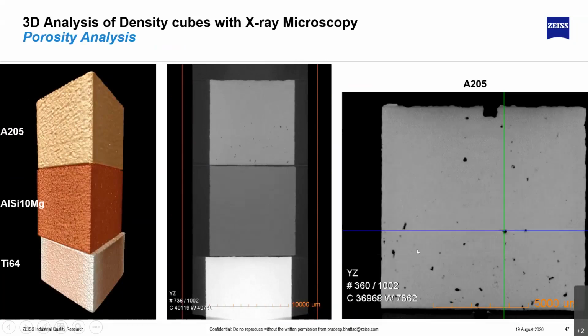So if you were to just take a cross section, if you look at the coupon at the top, if the cross sections were to come from the bottom or sit through the middle to the top, you'll get 3 different answers, and each one gives you an extremely biased answer, saying very bad, very good, to middling. So adding along with the tomography, if you add optical CT imaging, optical imaging, it tells you the sources of bias if there is any present, so you know how to deal with that data differently.